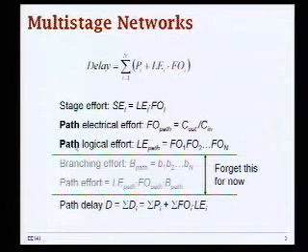And then you have path logical effort, which is simply the product of logical efforts of individual gates in the path. And those are the two numbers that you should remember. This is basically just an extension of the case that we had in the buffer chain example, when we had the total load at the output divided by the total load at the input. We take the nth root of that if the number of stages is n, and we say, well, that's our optimal fan out. But we have this additional term here for logical effort. That's what we need to worry about, okay?